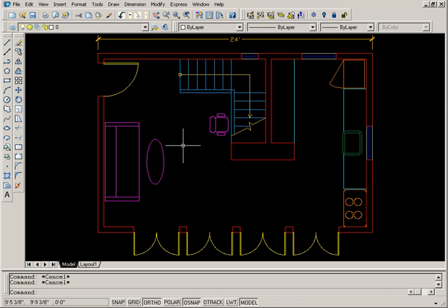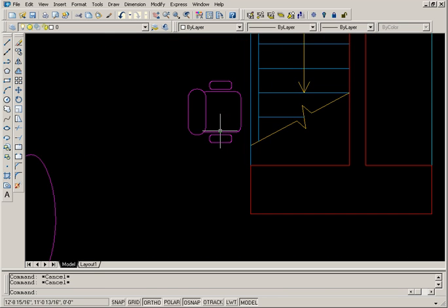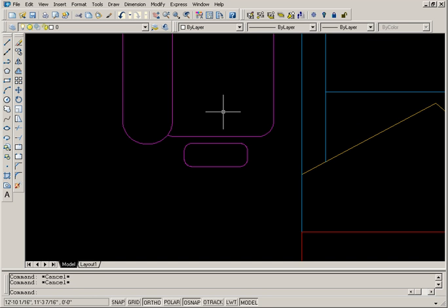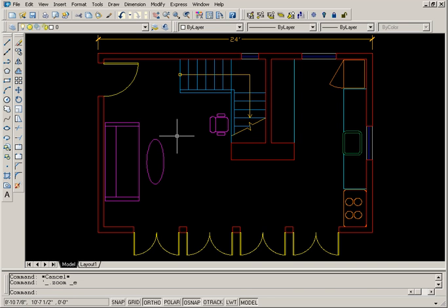In order to get this drawing into Photoshop, we'll need to convert it to an image. In other words, we have to take this vector-based data, which is independent of resolution, and take a snapshot of it in a specific resolution. In other words, we'll turn the math into pixels. In AutoCAD, the way to do that is to set up a printer driver.